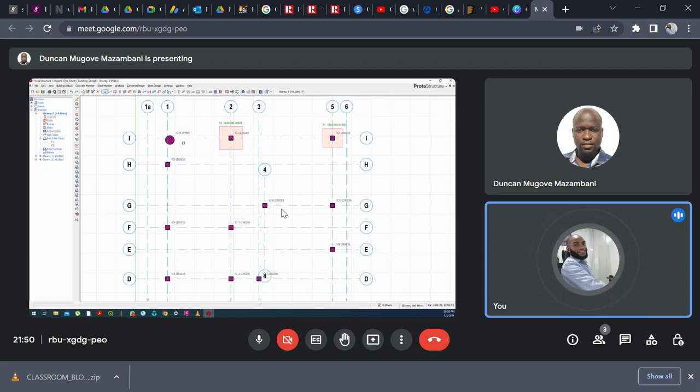So now to combine columns together for a footing base, you have to select those two columns together. Now right click and then you see the combine footing option. Say combine, you can see that combine there. Yes. Click on that. Then say yes. Okay, now right click and say insert part base. It will now design it as a combined footing. Yeah, insert part base.